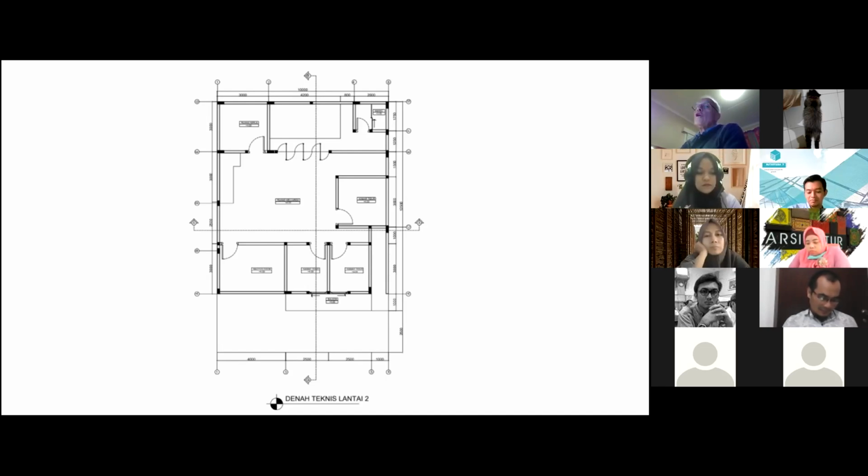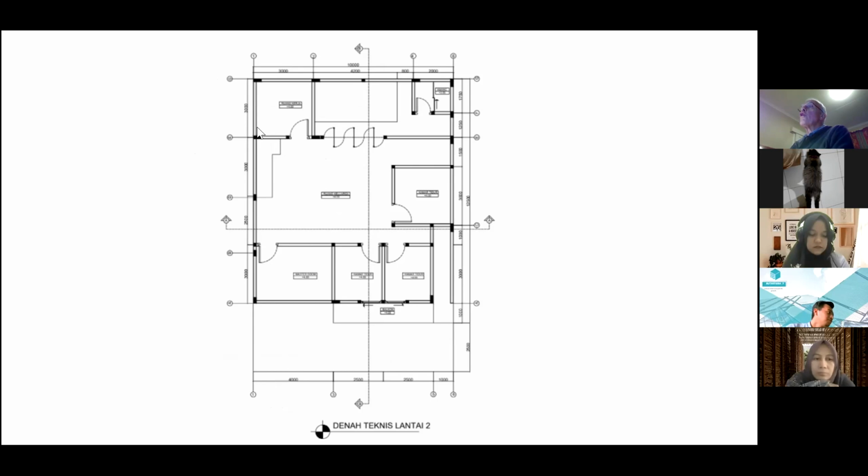So once again, if you have a wall that is continuous from the foundations to the roof, then that wall can help resist earthquakes. And so just to summarize, in the y direction, we have a wall on grid 1, which will be very strong because that wall is about 10 meters long. We have this shorter wall that is 2 stories high. It's only 3 meters long, but it will help a little. And then we have this wall here on, say, grid 5, which is 4 meters long. And finally, we have this very long wall here on grid 6. So very strong in the y direction.